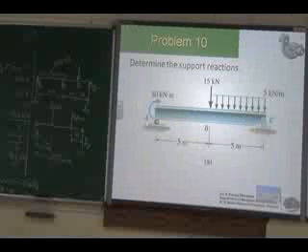First step, convert the UDL. Next step, free body diagram. Third step, take moment. Fourth step, take sigma F. Four steps are there. Okay. Support reactions need to be there. Support reaction.